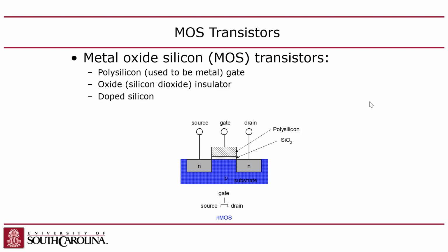I told you that the majority charge carriers in p-type silicon are holes, right? But if you build up a positive charge in the gate, it will attract, right under the gate, minority carriers in the p-type, which are electrons. Somehow, there's minority carriers in there. So even though p-type silicon is mostly holes floating around, you can attract the little bit of minority carriers in there, and they'll collect. And you might say, why? Well, because they're electrons. Electrons are negative.